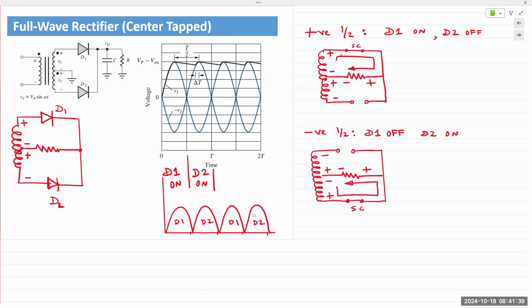If it's a very high frequency, you can place a capacitor in there. The point would be that if it's a very high frequency, the capacitor could be very small. But if it's 110 volts, which is what our purpose would be, the capacitor has to be very large. Typical power supplies, I've seen capacitors like, the wall warts that I was talking about, 10,000 microfarads, like really big. So 10,000 microfarads is what, 10 millifarads or 0.01 farad. So really big capacitors.